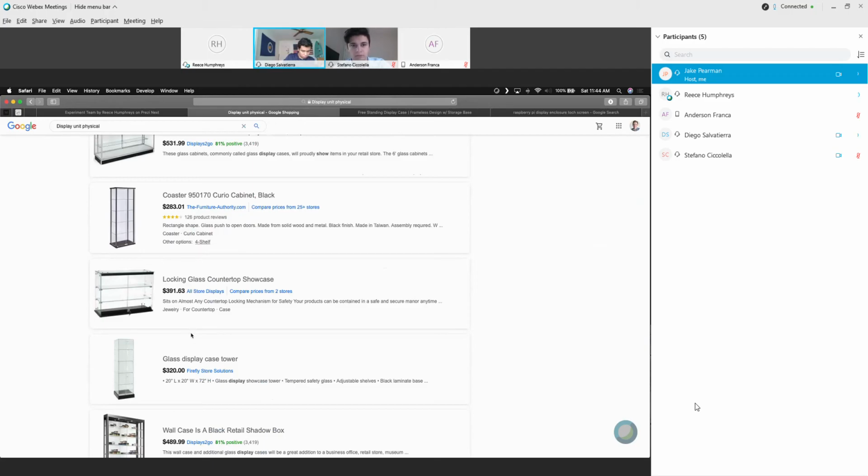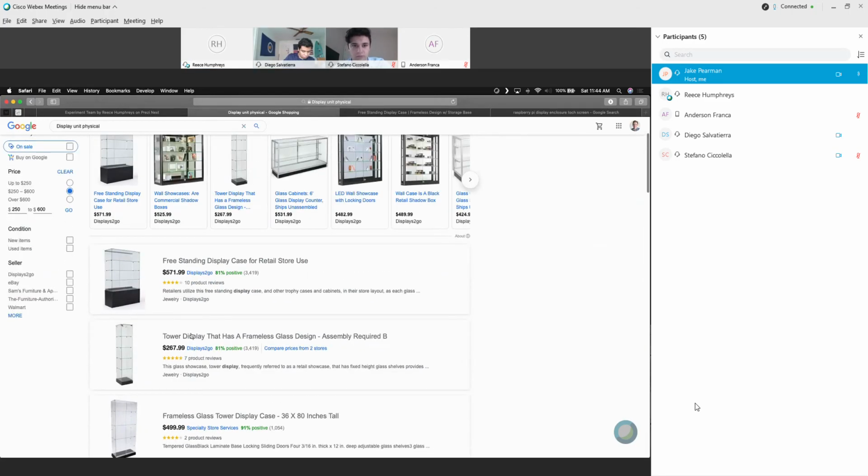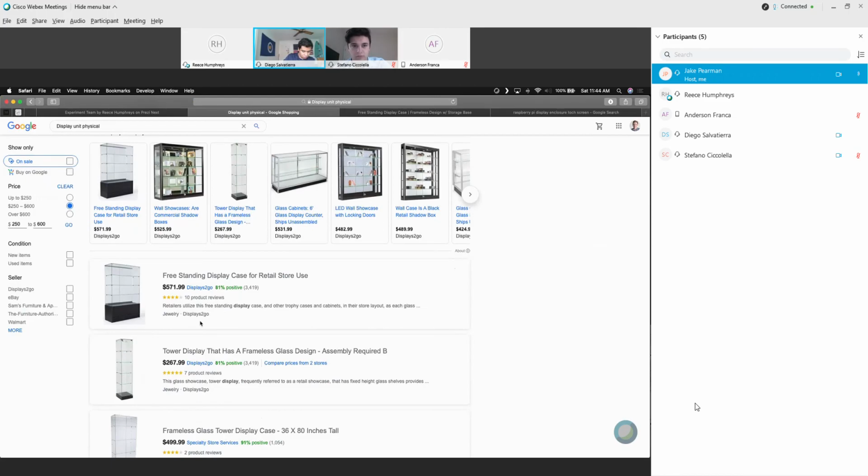If we wanted to record the satellite in low Earth orbit, expanding solar panels or reorienting itself, we can record that in the AGI software so long as we make it in the simulation and click record. And then you might be able to take that, I think it's an MP4, which is great. You can take that and put that on the Raspberry Pi.